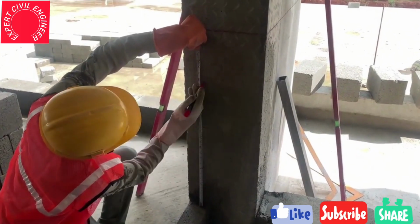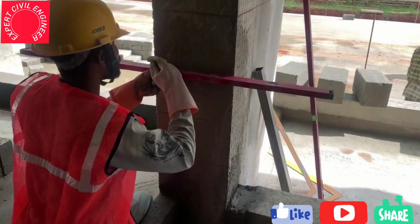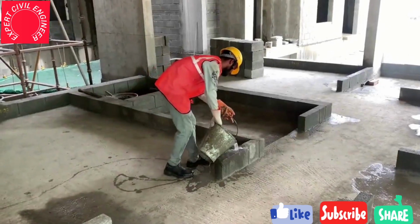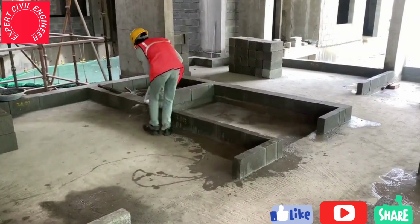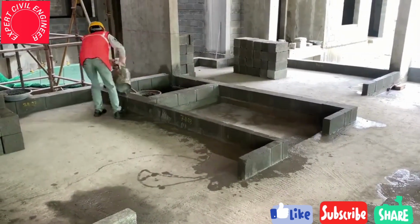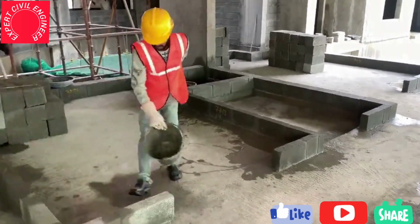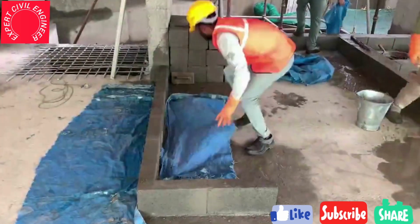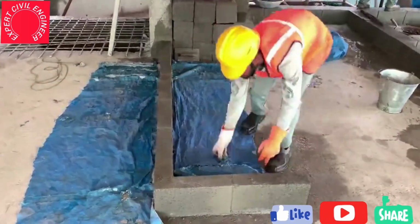Each course of blocks should be clearly marked on the column surface to facilitate proper wall construction and alignment. Curing should be done for the marker course before commencement of further works to ensure proper hydration and strength development in the construction material. A sheet should be laid along the wall where work is in progress on the floor to prevent the mortar from coming in contact with dust and mud during construction.